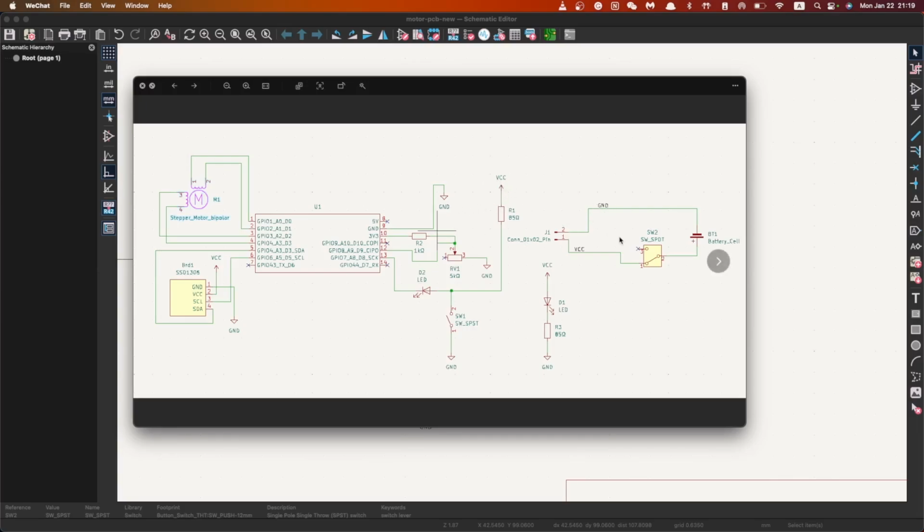The reason is that with these VCC labels being defined, we can use them to set the net class of different tracks, and the PCB editor can automatically select the desired width and other characteristics for our tracks to be created. Okay,